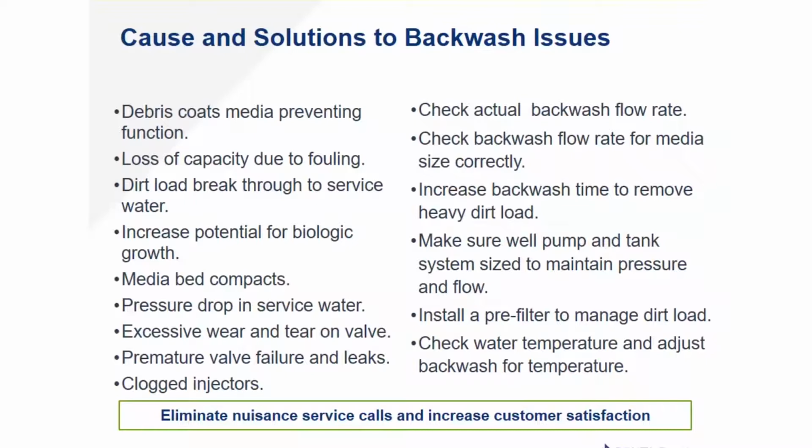Excessive wear and tear on the valve. Remember, this is all particulate. And if we're leaving too much particulate in the inner workings of a valve, you're going to wear and tear on those pistons and seals and spacers over time if you're not backwashing long enough. Especially if that debris is sand or iron particulate, rust particles, you're going to have more of an effect there. Premature failures and leaks, clogged injectors. That's how I found my issue with my backwash: suddenly my injectors were clogged and I was getting hard water.